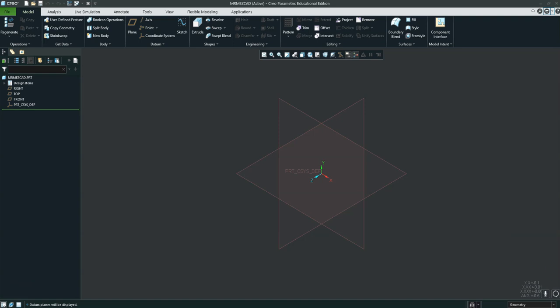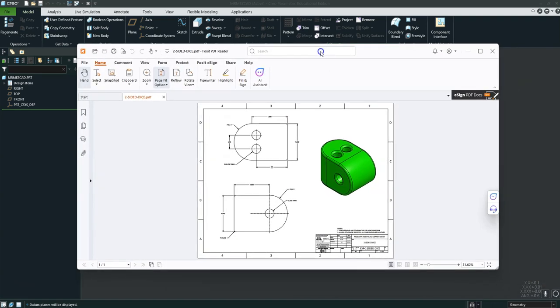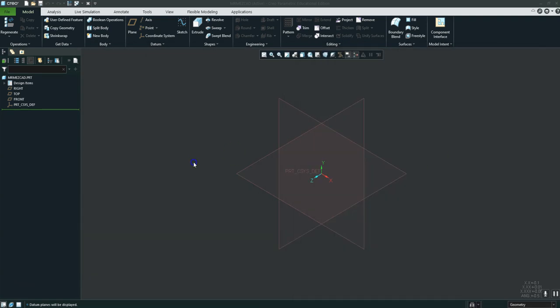All right, now I have a drawing that I'm going to look at on the side that I've created that my students are going to work off of, but I will give you all the dimensions while we create this. It'll be a nice short video. So first thing we're going to do, we're going to go up to the top, make sure we're on the model tab up here, and then we're going to go over to Extrude.